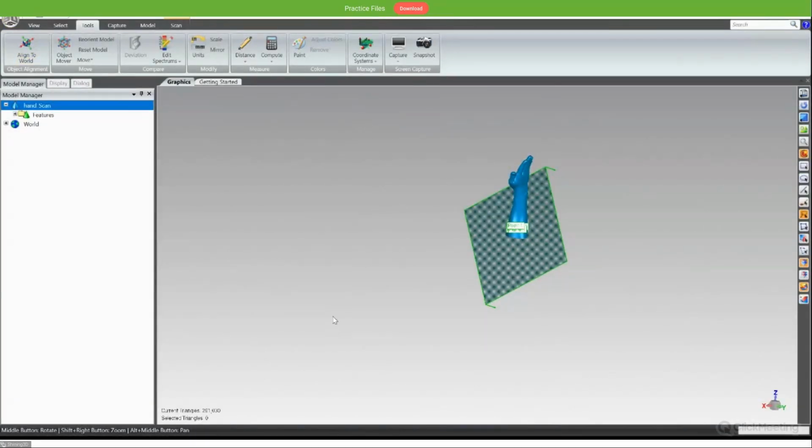I recommend exporting it as a single file. When you tick this, all the features and lines you have drawn or created by auto surfacing will be saved in one IGS file, and you just open it with SolidWorks. You have the layout of all the features. This is very simple. Don't forget to tick this part.